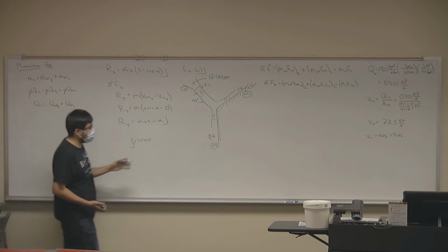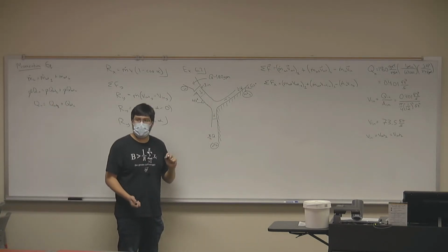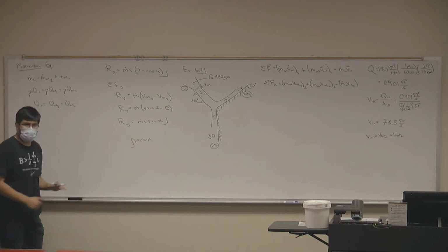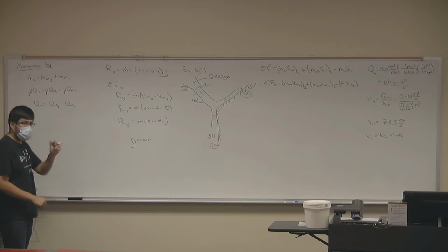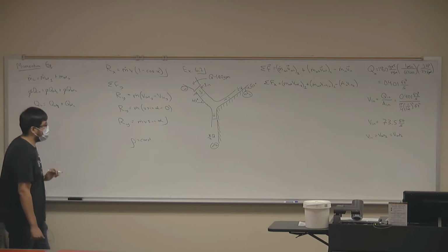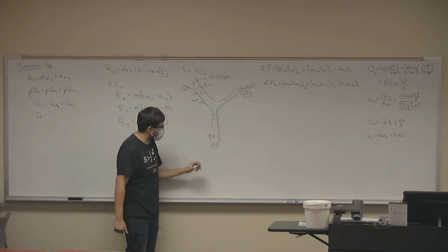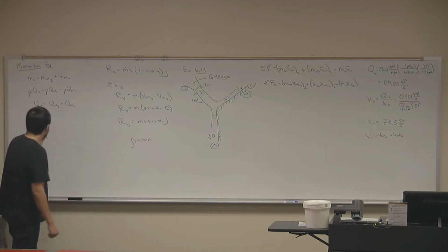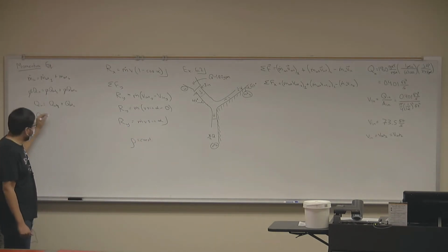But notice that even if we didn't have both distributions, we could still figure out all three of these flow rates as long as we have flow rate in and at least one of those distributions, right? We said that through the first outlet, only 3/4 of the flow rate travels, which means that flow rate out 1 is simply equal to 3/4 of flow rate in.